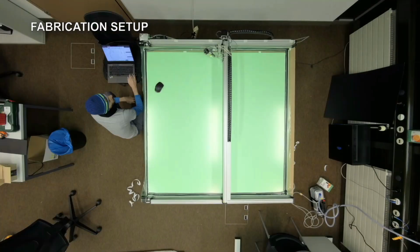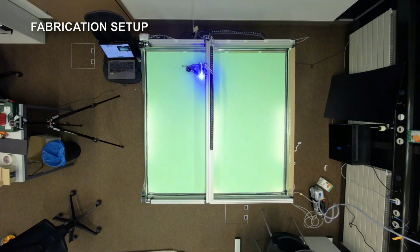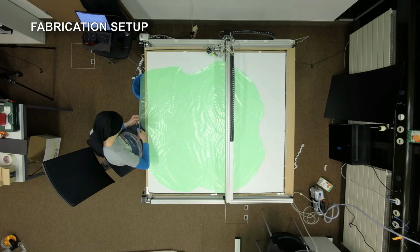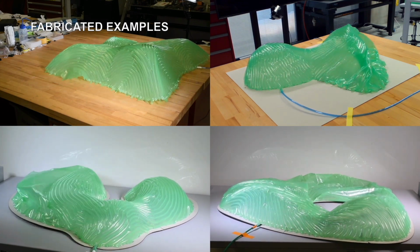We fabricated several prototypes generated by our algorithm using a custom machine consisting of a laser mounted on a CNC plotter. We used 75 micrometer thick polyethylene film as the sheet material, and the machine is capable of fusing designs up to 1.3 meters by 1.3 meters. Here are some of the architectural surface style prototypes we fabricated.